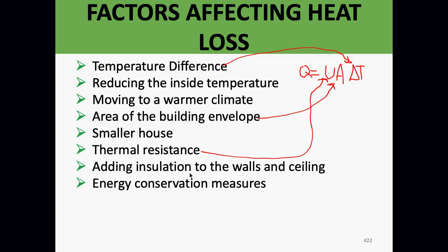If you're able to install, let's say, an R19 in a 2x12 rafter, and you put it in properly, it's not compressed, and you leave about an inch airspace and put another set in without compressing it, is it still reducing it? Or is it only reducing it because on average you're compressing some of the original? If you leave an inch airspace, you'll be okay. It's the airspace that makes a difference. If you put it right on top of each other, you're going to reduce it. Remember, air is an awesome insulator as long as it's there and not moving.